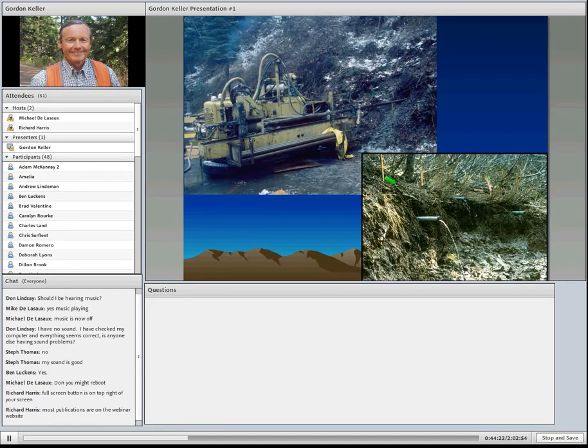Horizontal drains, they're mostly used in deep-seated landslides. We've used them quite a bit. If you can lower that water table on a large landslide, you can maybe spend $50,000 on horizontal drains compared to spending $250,000 on a retaining structure. So it's really lowering the water table. So you've got to hopefully see some results and be getting some water out of the system. You don't necessarily have to get a lot of water out, but at least you have to lower that water table for horizontal drainage to be effective.